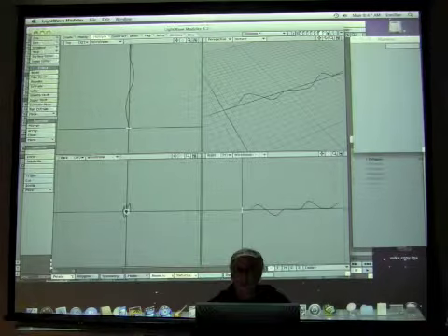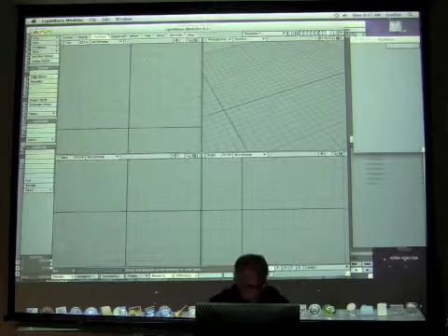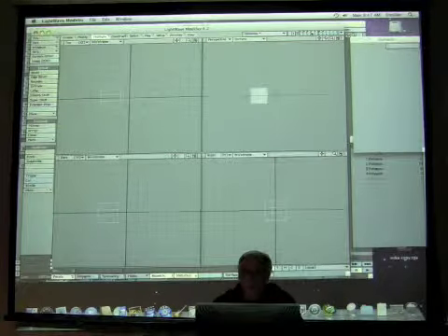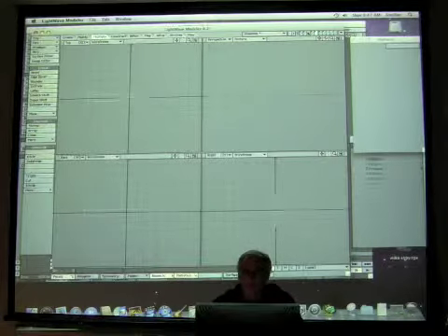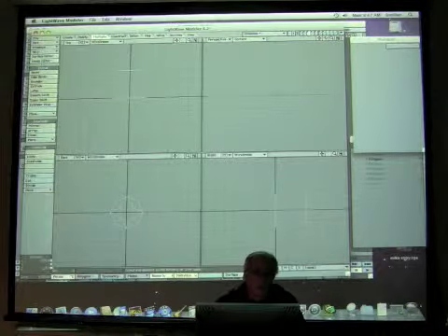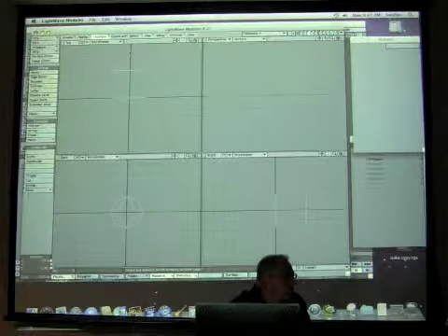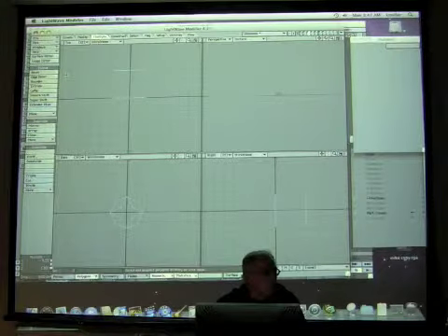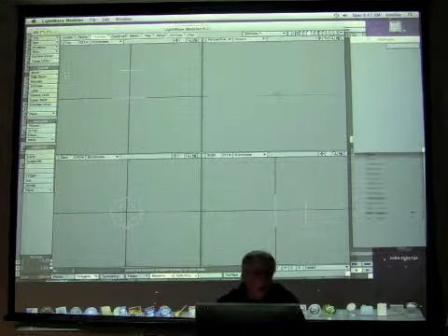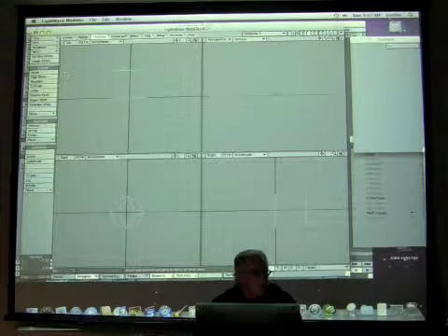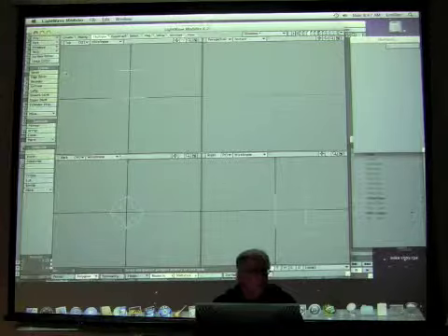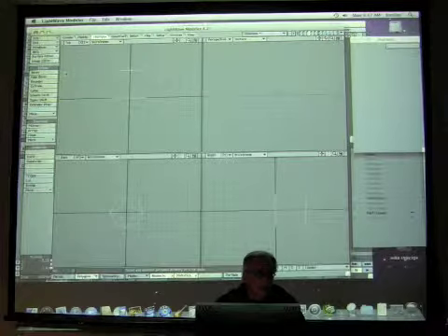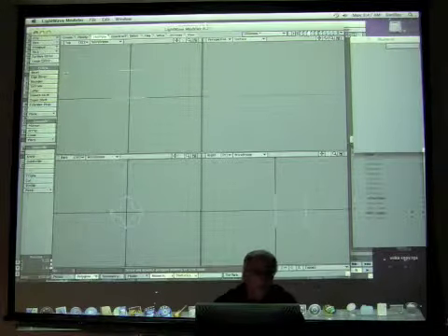So, next step, I should probably start deleting some of these. I want to go back here for a minute, because remember I had, where was it? This one. I think you have to be in polygon mode for the skin. Is that where I messed up? It could be. It's one little thing that can mess you up. I do know that for skin, you have to have two individual two-dimensional shapes. They have to have the same point count. They cannot have a different point count. And that will work. So let's try again.